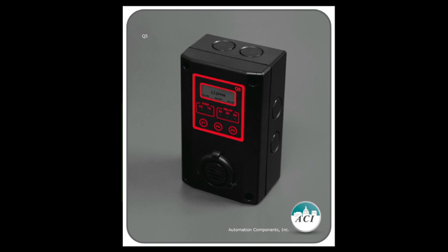What's nice about this is that it has a replaceable sensor in the front, so if you have a CO sensor on the shelf and you get to the field and realize, oh, I needed a NO2 sensor, you can take the circuit board and the sensor off, right off the front cover, pop in the NO2 sensor, and it's already calibrated from the factory, so you don't have to set up anything in the field. It has knockouts on each side, 2 knockouts on each side of the cover, or on the top, bottom, left and right side.